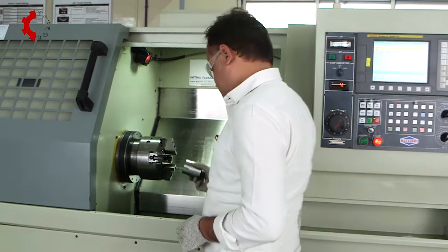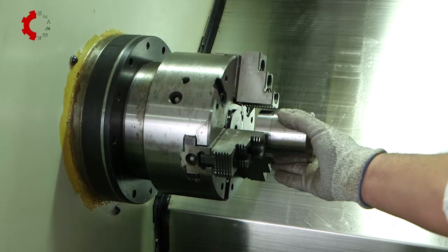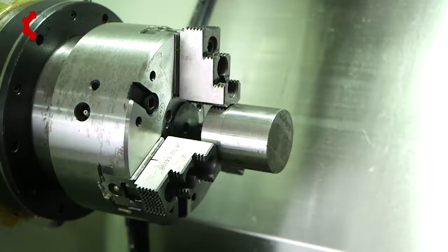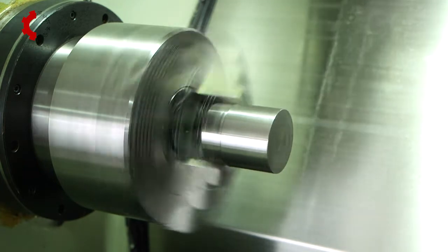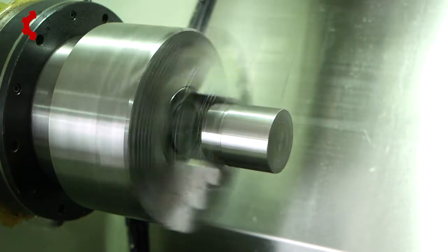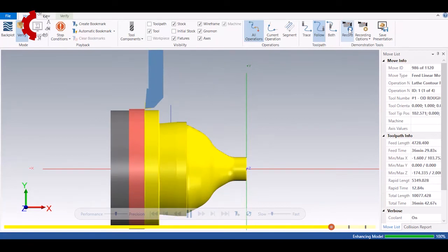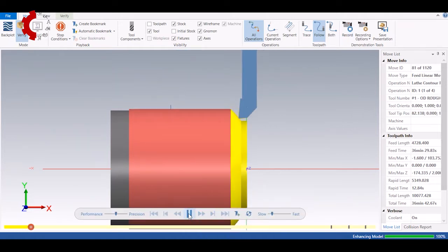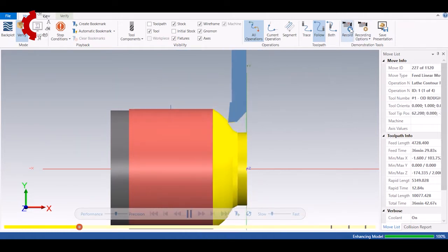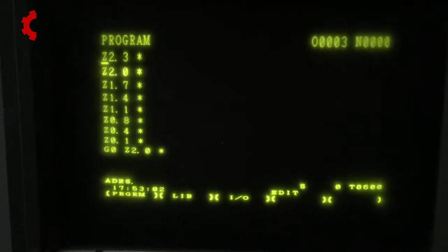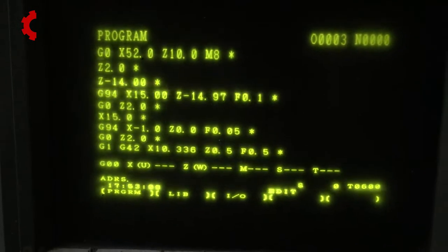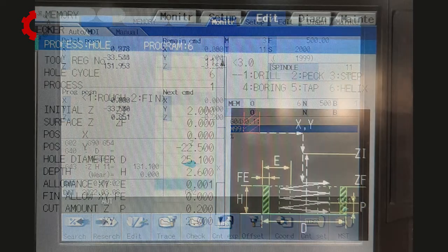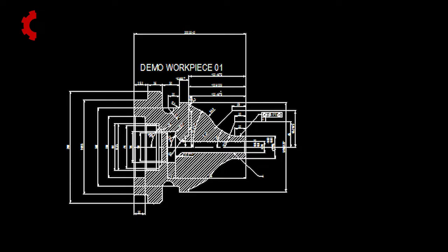In CNC turning, the workpiece is held firmly as per pre-designed configuration and rotated at the required RPM, which may vary as desired. Tools are moved along the workpiece as per the desired profile, the required number of times. This is executed exactly as instructed to the machine with a set of sequential instructions called a CNC program. The basis of tool movement is two-dimensional coordinate geometry. Programming is done based on the component drawing.